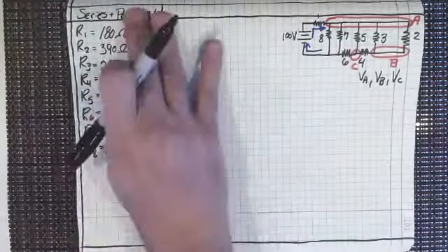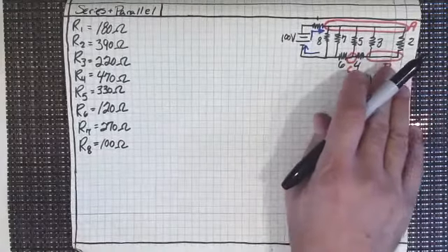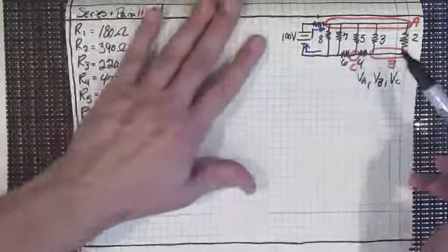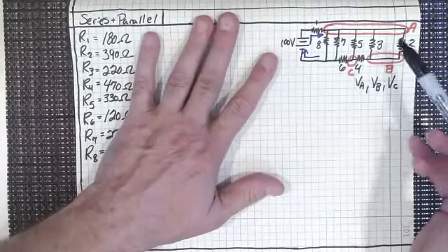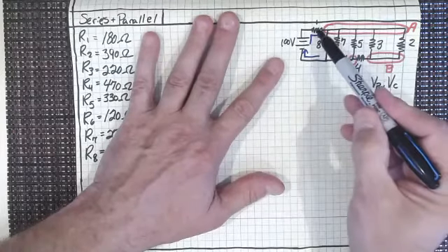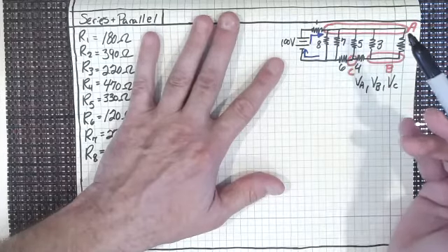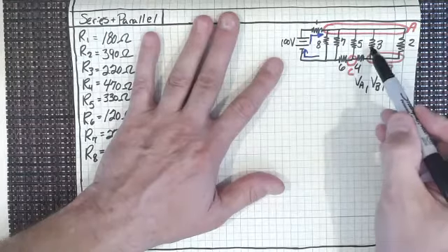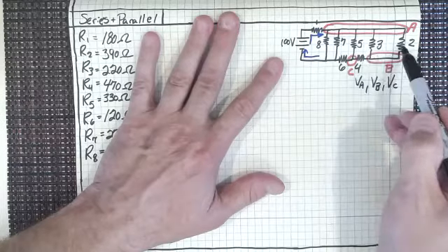So I've just picked 8 different resistors, and we originally had them in that configuration that we had in the last lecture. I've just picked some resistors here. We now have them in this, and we can still simplify this further, can't we? Because I think you can see some things that are in parallel and some things that are in a series, right? So if we look down here, we see that these 3 and 2 are in parallel.